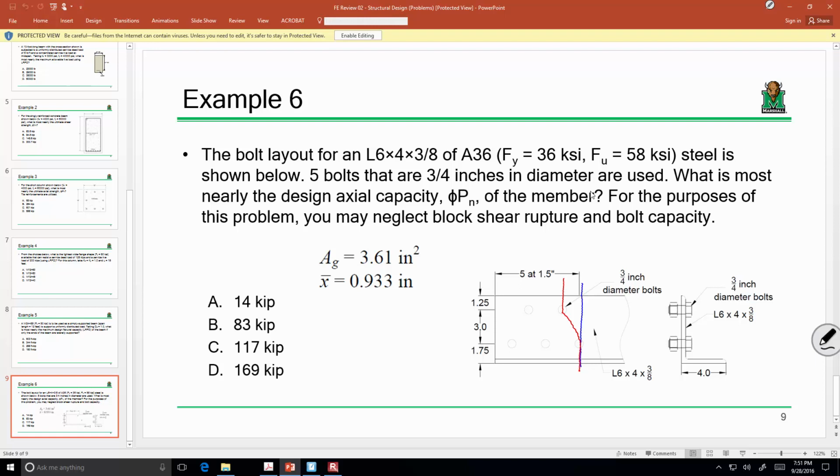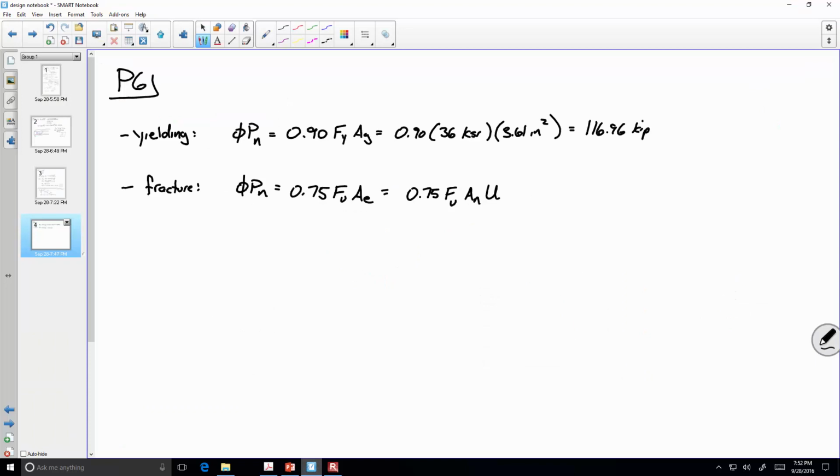Two. So here's the difference. My first path, I'm only subtracting through one bolt. The second one, I've got two bolts, but I have to add a stagger factor. And we'll see what that is here in a second. Okay. So I want you to look here over that left-hand column, and we'll see how this goes. Okay, net area.